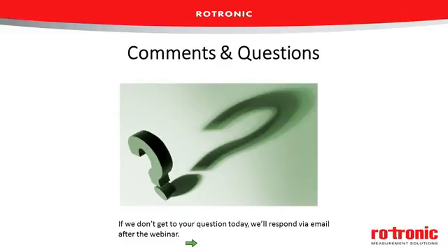Okay, we might have room for one more question if we have any. David, I got one more question, and it has to do with speed of response. Dan is looking to know about RH measurement in an apartment. So we'd be looking at a residential and office environment, obviously, and he wants something that doesn't take 20 minutes to get to an RH reading. And I would venture to say that has to do with airflow, wall mount sensors versus maybe something a little more quick to respond than a wall mount. What do you guys think?